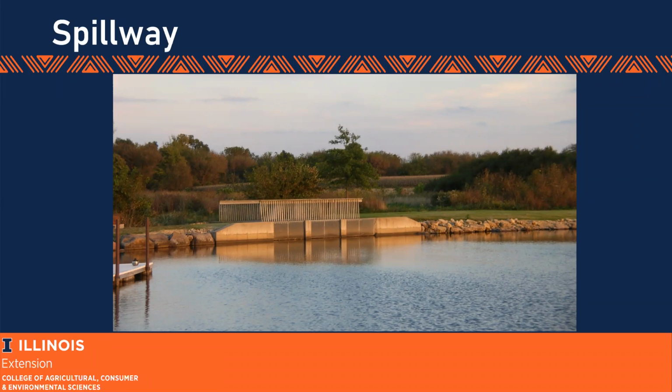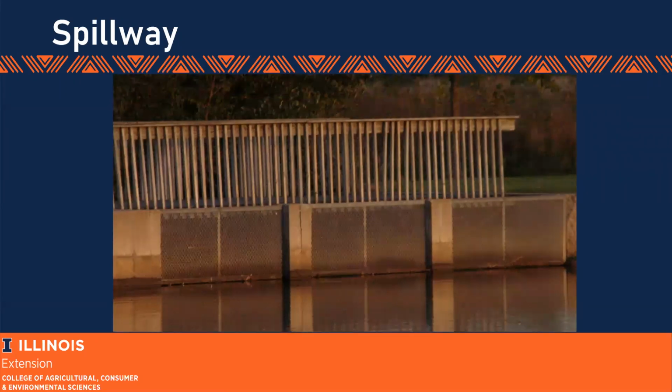And rather than trying to catch that bigger stream, which would have created too big of a lake for them, would have created a lake instead of a pond for them to manage. So in this case, they designed it to catch a specific amount of water and then designed the rest of it around it. Now, another unique thing about this one is that it's the primary spillway and also the emergency spillway, and a little bit of thought went into keeping the fish in there.